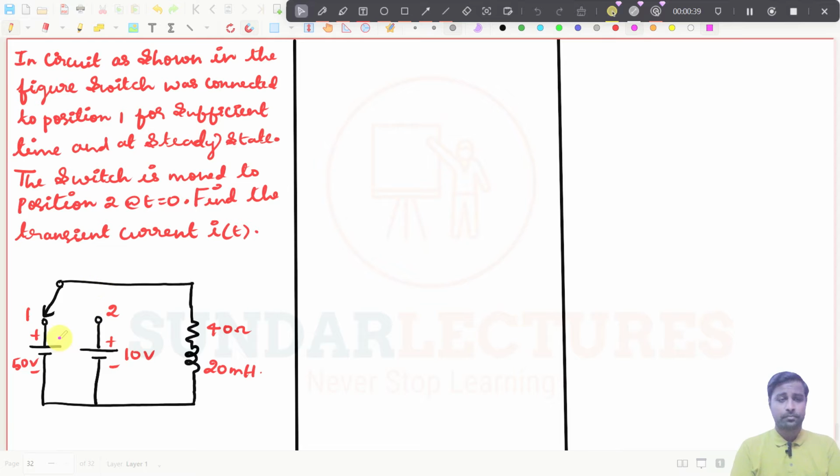See here, switch at position 1 is the first case. If the switch is at position 1 and it has been said that it is for a sufficient period of time and at steady state, what happens at steady state? What is the current flowing through this inductor? It will be E by R, right?